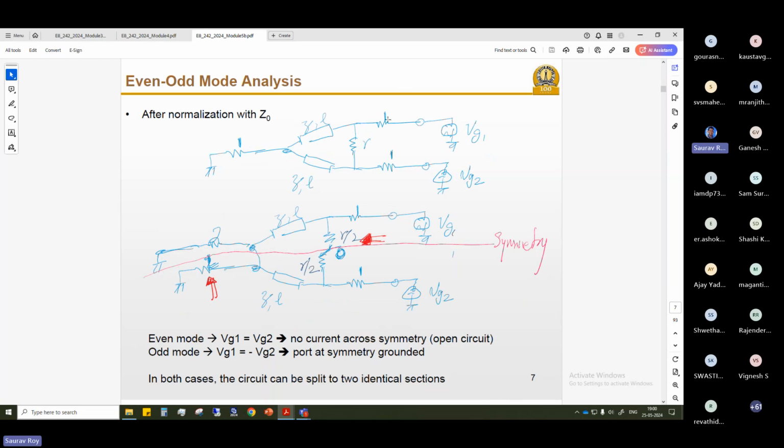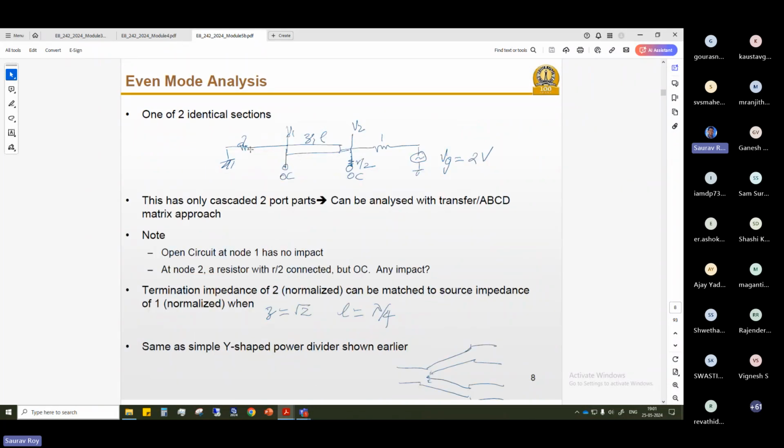And the interesting thing is, if you see, we have taken a value of 1 for all the resistances, R. This is generally normalized. Generally, in microstrip line calculation, we normalize with Z0. Z0 is generally 50 ohm. So that's why 1 means Z0, 50 ohm, and 2 means 2Z0, 100 ohm. See here, 2 comes because 1 we have divided parallelly between 2 and 2. So that's why 2 means 2Z0. It has been normalized.